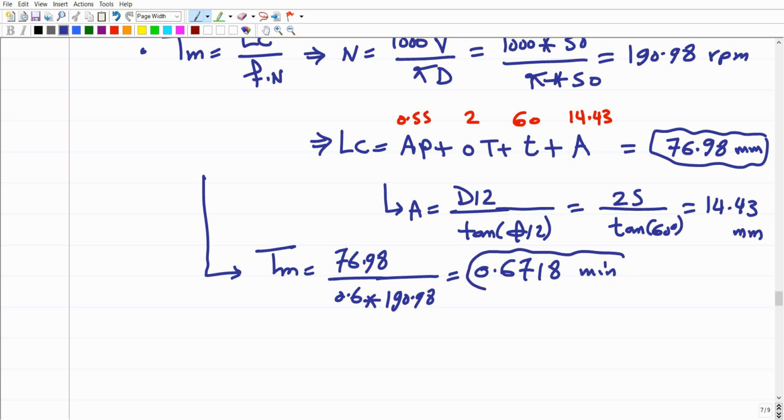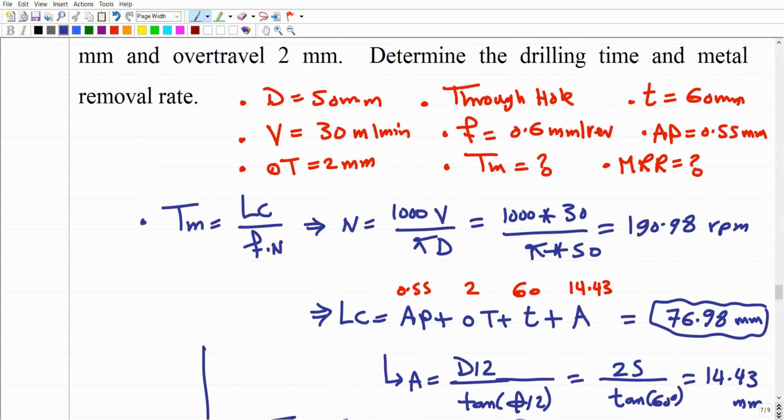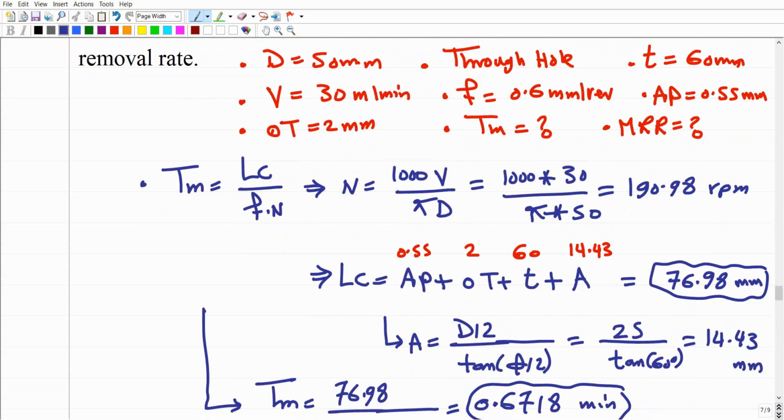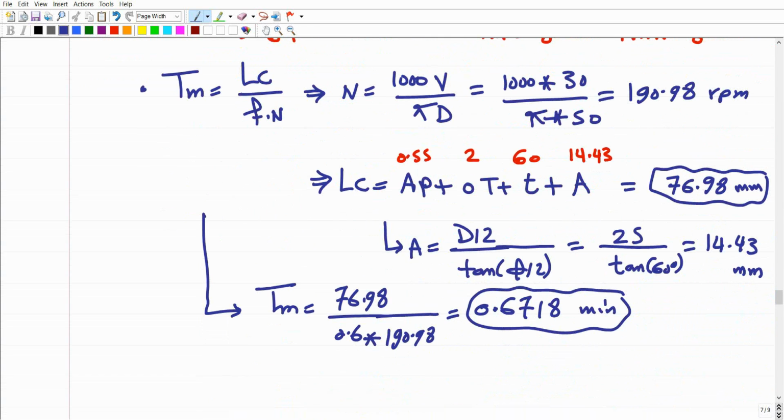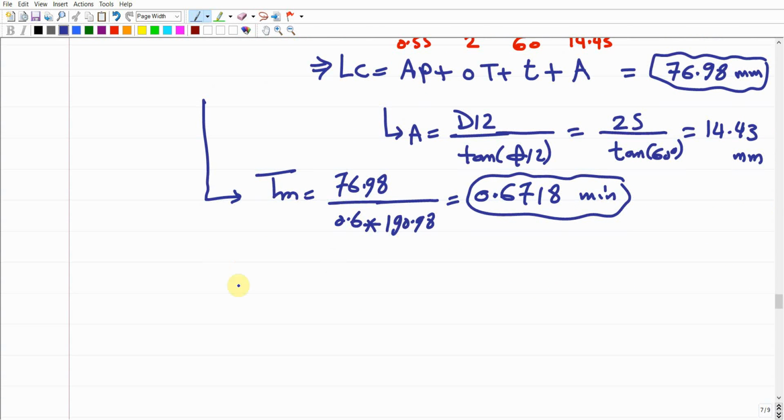This is going to be the machining time to open this one single hole. Assuming that we do have 100 identical holes that are going to be done with the same twist drill with the same cutting speed and feed, what should be the total machining time? Multiply this machining time of a single hole times 100, which is the number of holes. Make sense? But here this was not required, so anyway we're going to have only one machining time and that's it.